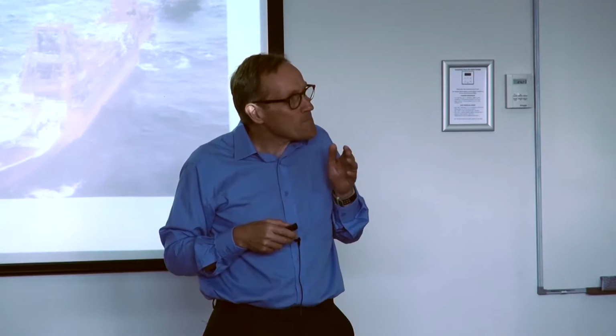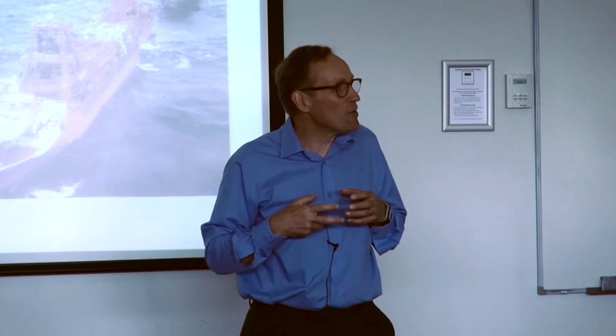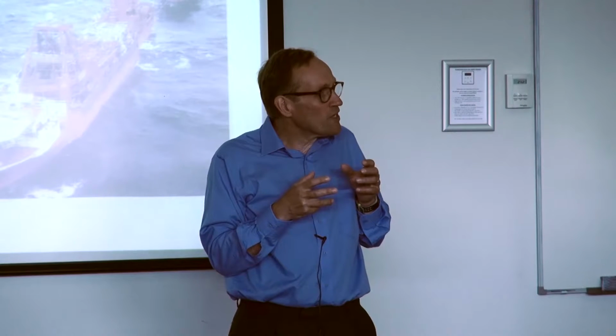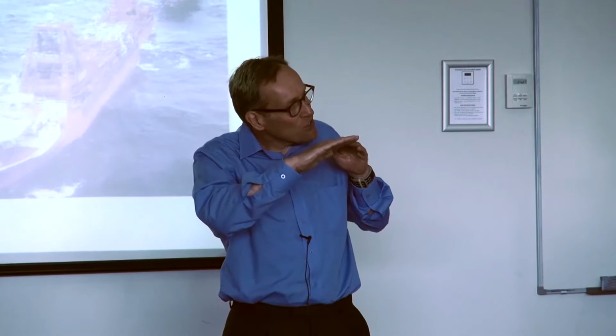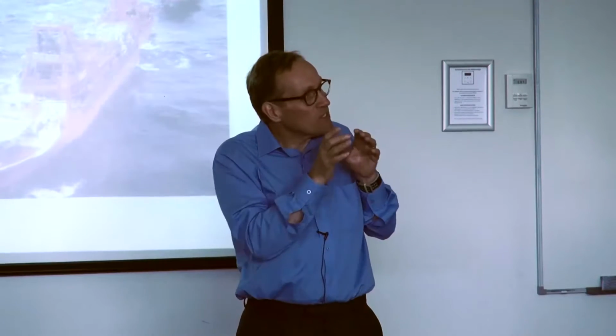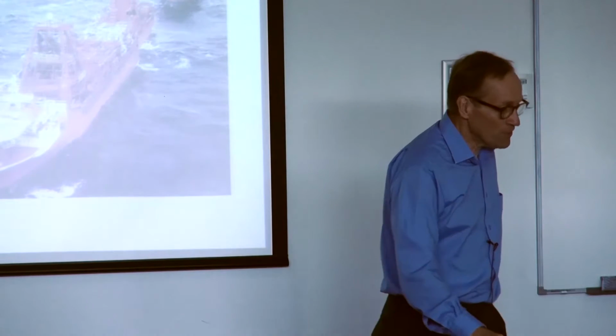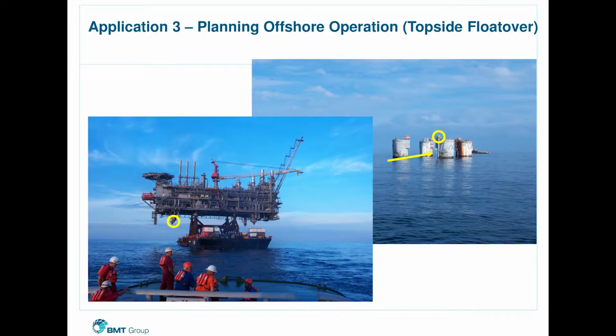So we need much more information about the physical environment. We're concerned not only with the wave height and the water level, we're concerned with the current and the wind, and we're concerned about the combination of those factors, how the assembly aligns to the joint influences of current and wind, what the relative motions of the shuttle tanker and the FPSO are, the loadings on all of the subsea infrastructure.